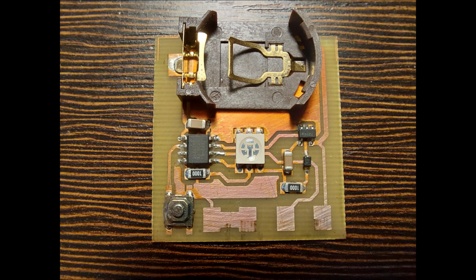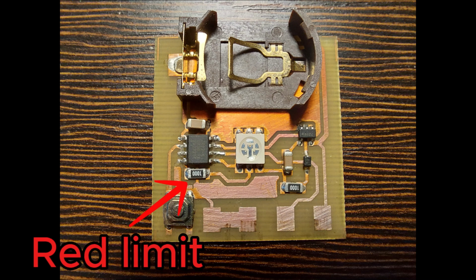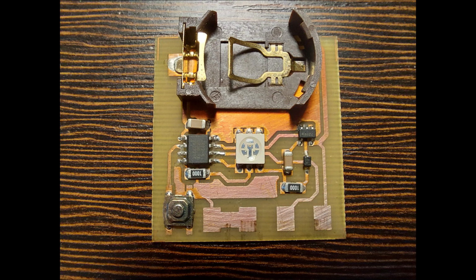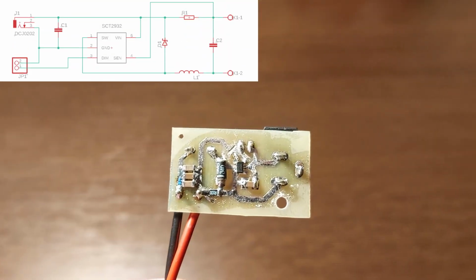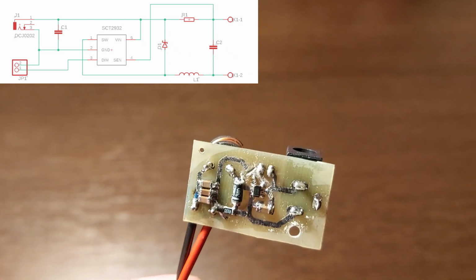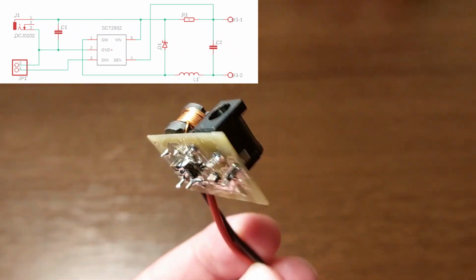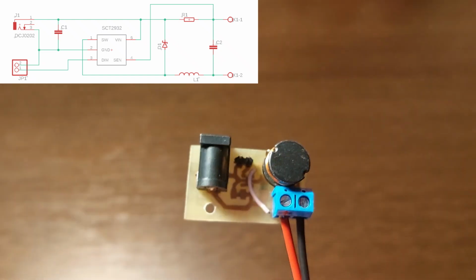You can also use this resistor to adjust LED brightness. For example, it may happen with RGB LEDs that one color is stronger than the others, so you may want to trim it on hardware side. But if you're using microcontroller, you can also do it on software side, whatever is more convenient. There are more efficient methods of keeping the current on some given level, but they are also more sophisticated, so it's well beyond the scope of this video.